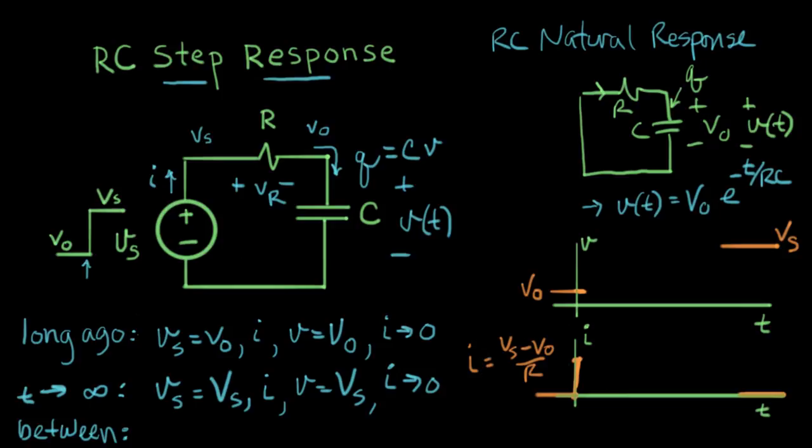All right, so we got our current to hop up. And now there's more charge flowing onto our capacitor. So the capacitor voltage is going to start changing. More charge, more voltage. And what's going to happen, we can estimate this, it's going to just do something like that. I can sketch that in. More and more charge will start flowing onto this capacitor, and the voltage will gradually rise until V equals Vs, till the voltage across the resistor, again, is 0, and then the current will stop.